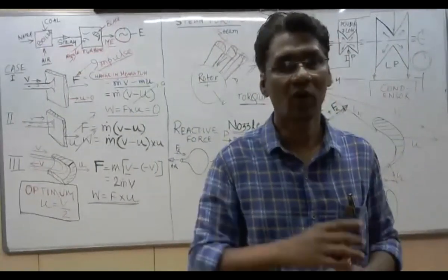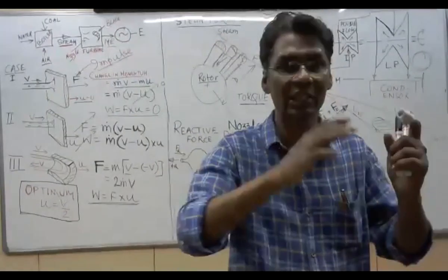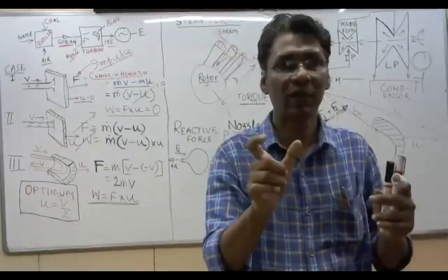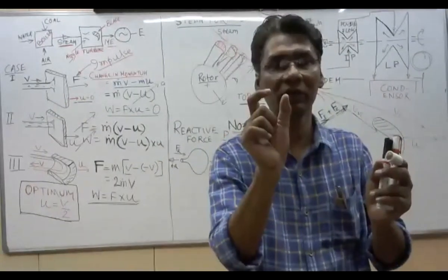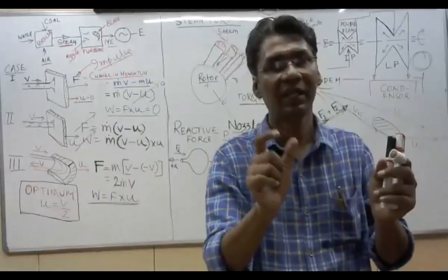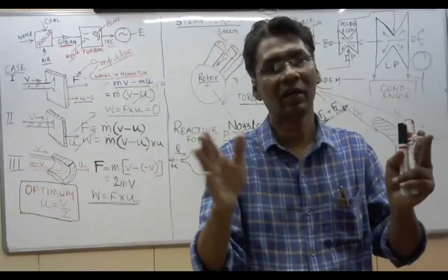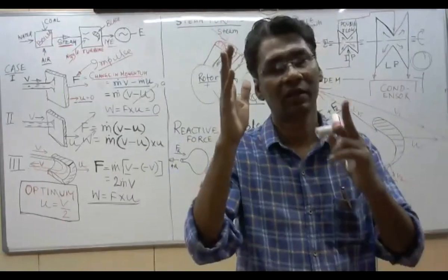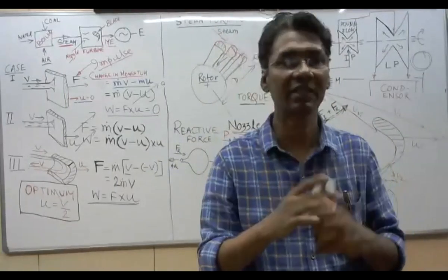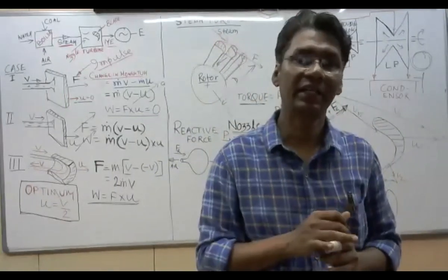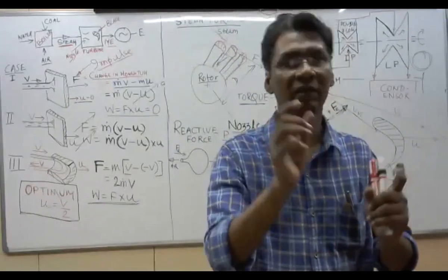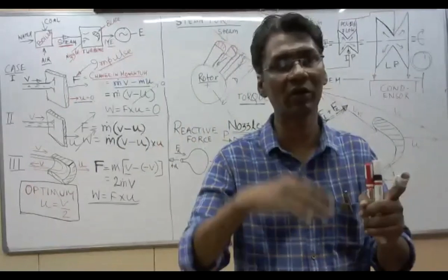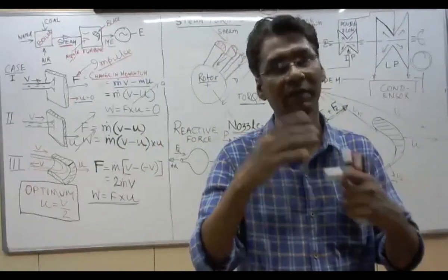There is no expansion of the turbine, there is expansion of steam. The turbine expands thermally by a very small amount, that is called turbine expansion. Rotor expansion minus casing expansion is called differential expansion. That is not controlled, it is allowed, and how much expansion is allowed is maintained. Beyond this, the turbine will trip and be stopped.